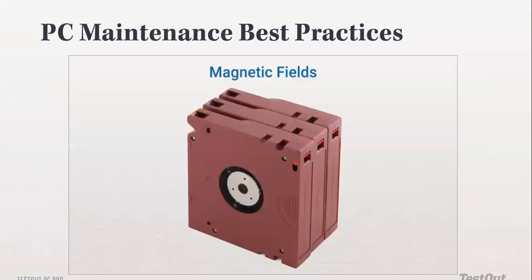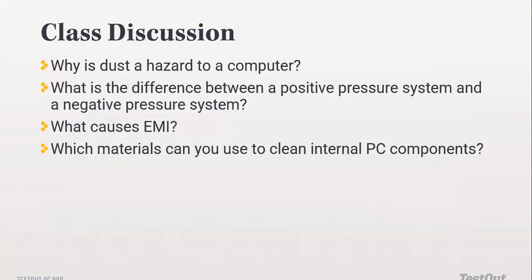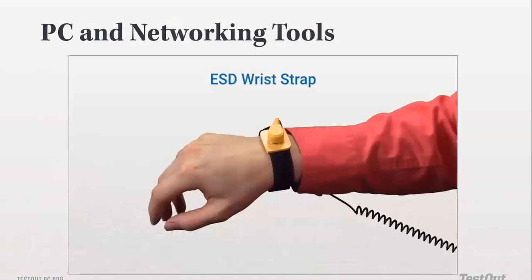Within your work environment, the proper temperature you should maintain is between 70 degrees Fahrenheit and 74 degrees Fahrenheit. I think you can convert that to Celsius. The humidity should be between 40 to 70%. Previously, we said 40 to 60, but 70 also is not that bad. It should not be excessive because we are going to experience condensation.